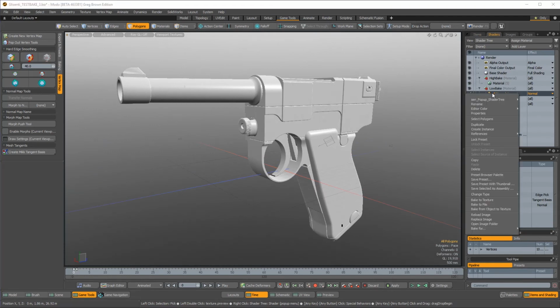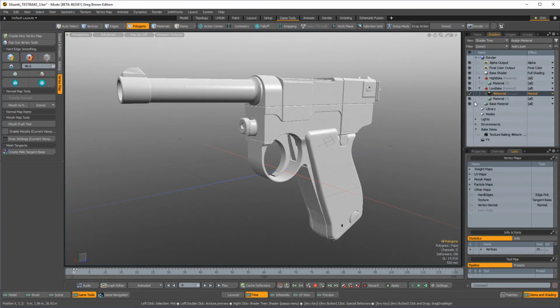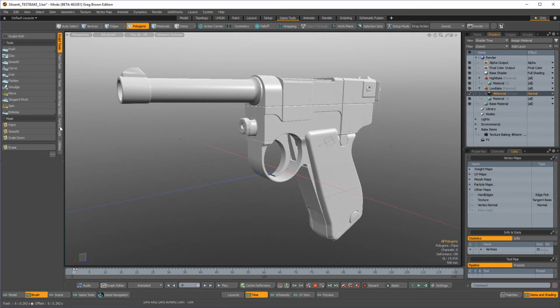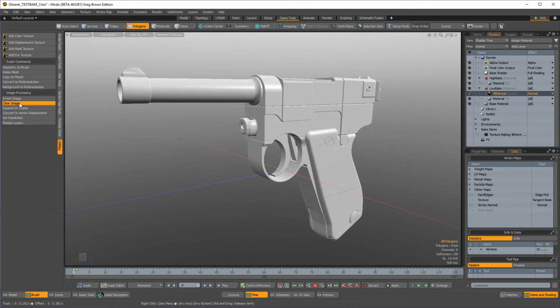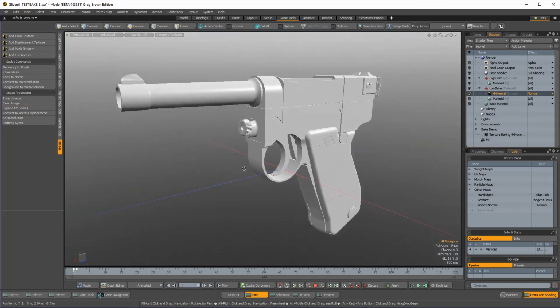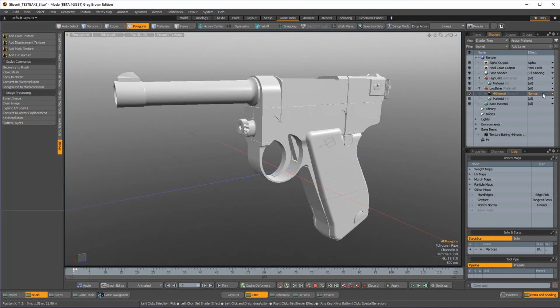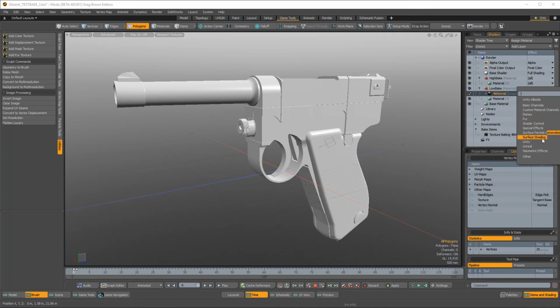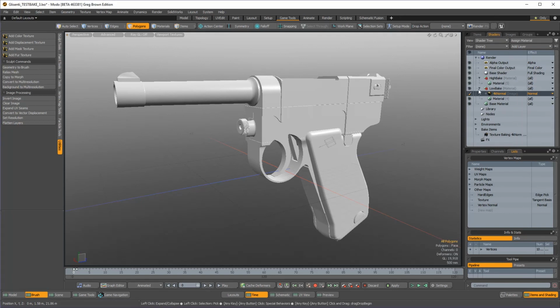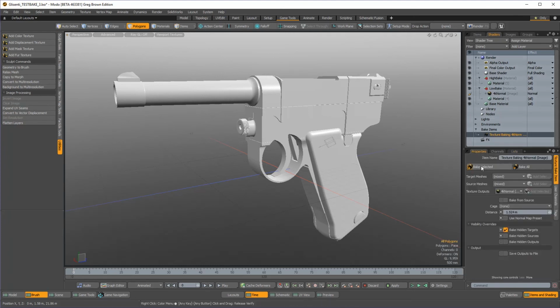Now let's go ahead and, you know what? I want to clear this image. I can do that easily by coming up over to the brush settings, come to utilities, and I can clear my image. And then my shading will go all sorts of wacky or just be nothing. Good, awesome. And I am also using Modo's default normal maps. You of course could, if you have the right material in place, change that to a Unity normal or an Unreal normal map.